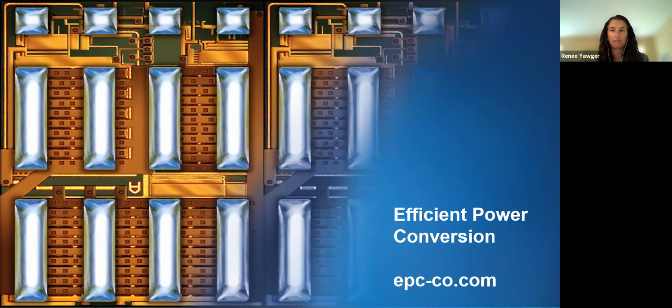Mm-hmm. That question hasn't really come up that much because the GaN FET thermal resistance from the junction to the case is very small. It's like 1 point something in a lot of cases, degrees C per watt. So it seems like we don't see that big of a difference.